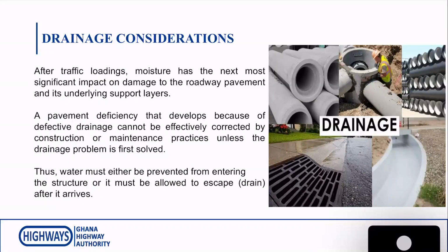Now, after traffic loading, realize that the next most important damage that affects our road pavement is moisture. So if you have water in your road pavement, then you are in serious trouble. One always has to be careful about moisture in the pavement. If you have a deficiency in your pavement that is developed because of defective drainage, you cannot correct that by maintenance works unless you have solved the drainage problem.